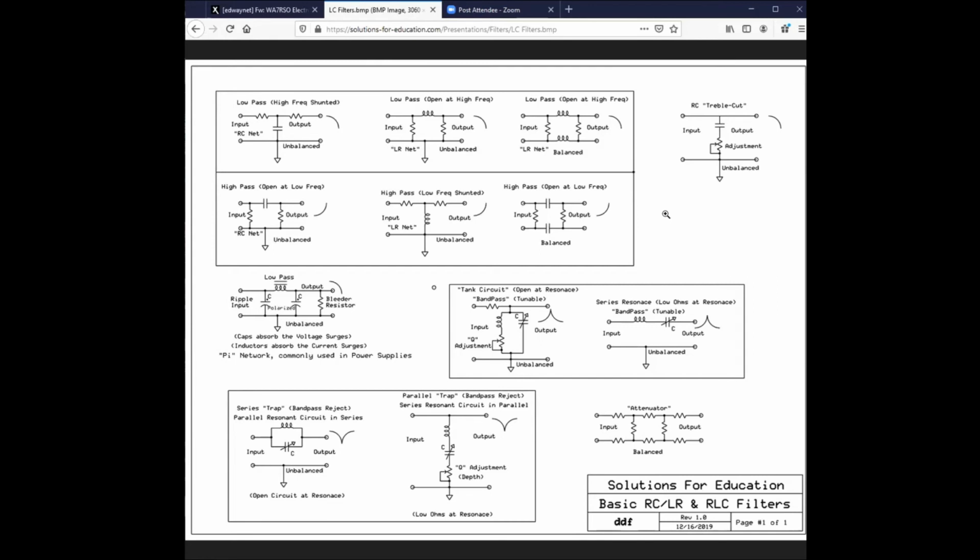And then while that tape was looping around, we would run what was called a tracking filter, and it would look at a certain bandwidth and a certain pass band, if you will, as you would take the filter and run it through a range of frequencies. This particular very expensive filter could be controlled by voltage, but more often than not, we had a signal source that we would put into it, and it would follow the signal source for the frequency that we were interested in. That's how we determined what energy was being transmitted from one end of the missile to the other, through the skin or through the innards in some cases.